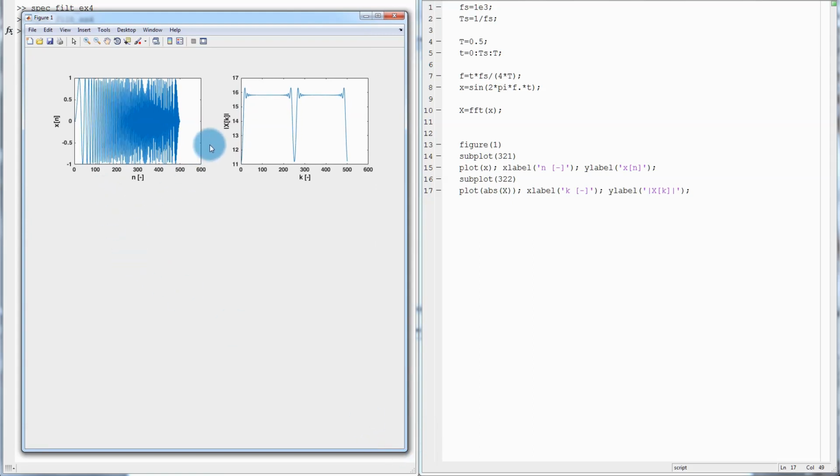So what I have here is the chirp signal in the time domain. On the horizontal axis I have my time indices, and this is the discrete Fourier transform spectrum of my chirp signal. On the horizontal axis I have those discrete Fourier transform indices k. Now remember, MATLAB gives me one period of the discrete Fourier transform spectrum with length equal to the length of the signal.